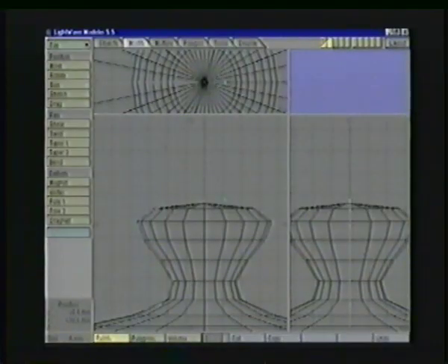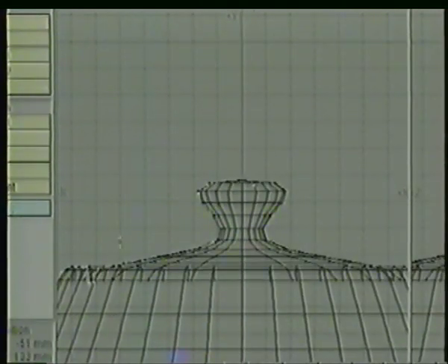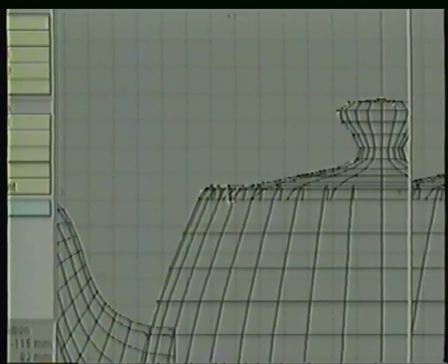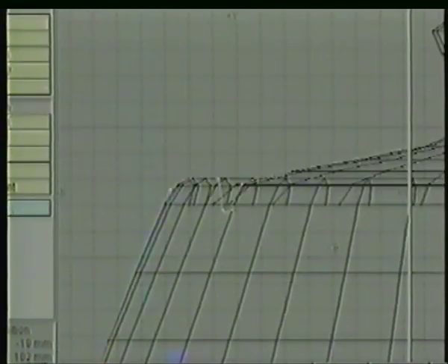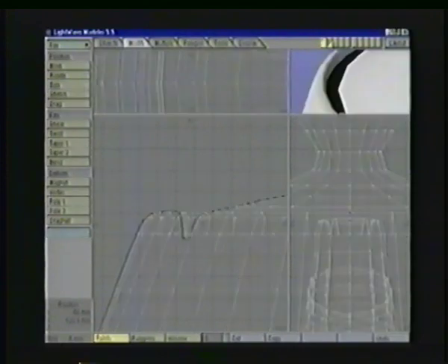And once again, I'm going to grab that point and move it around until I'm happy with the curvature of the top of my lid. I'm going to zoom out with the comma key again and center over the left side with the G key and zoom in one more time. Because this is where the lid meets the edge of the pot, and if we look again, I'm going to swap layers with the apostrophe key on the keyboard so we can get a better look at this.